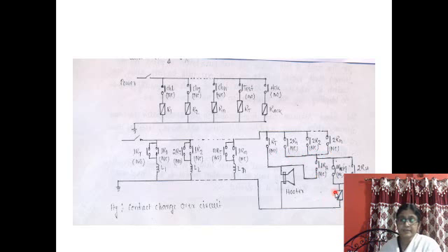And how will that get power? There is a hooter contact 1RH, that is NC type contact. This is R acknowledgement, the contact corresponding to this relay. The test switch and acknowledgement switch are external switches operated by the operator, so all these are NO type.